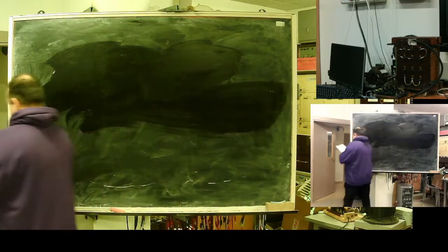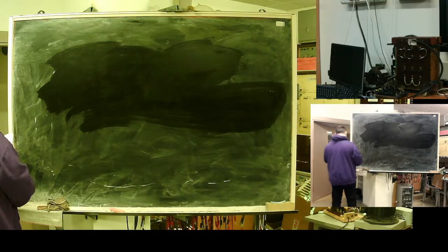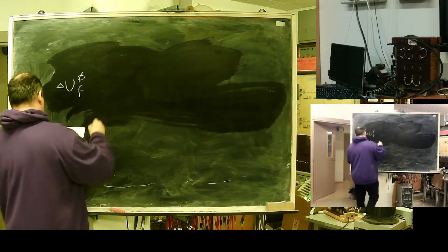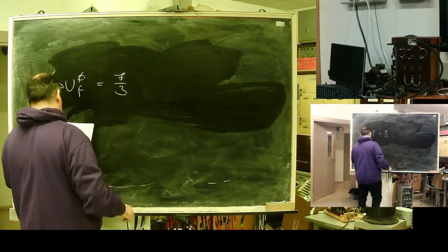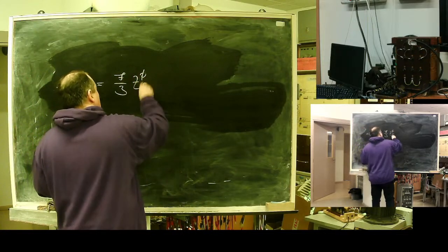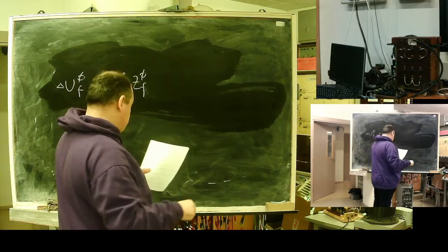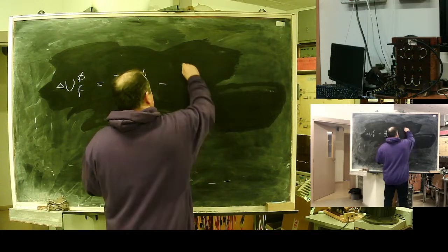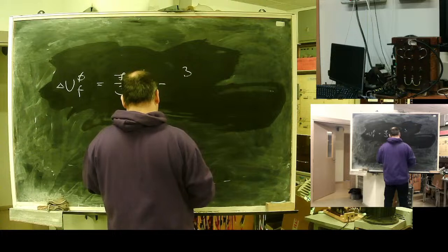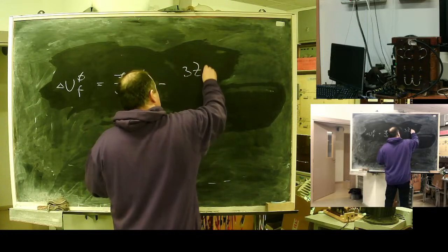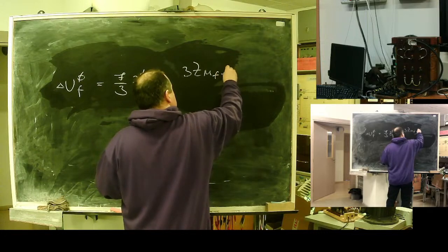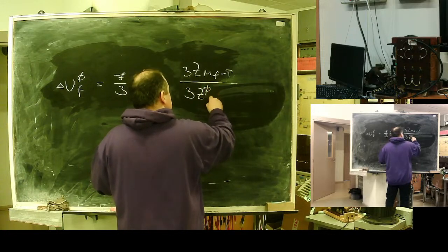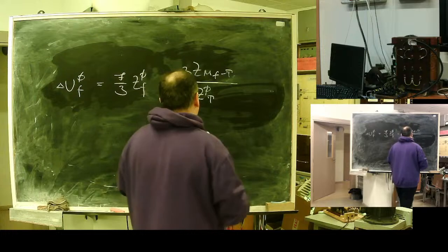And now we get the zero sequence voltage drop: 1/3 of the current source, self zero sequence resistance of the wire minus the mutual resistance phase to wire divided by triple zero sequence self-resistance of the protective wire.